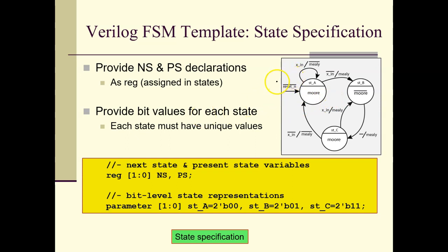But important things in here is how to represent this thing. First thing you see up there is the state bubbles. So how do you represent the states? This is how I do it. I got this line here where I declare two types of register variables, and then down in this line right here, I define my states.